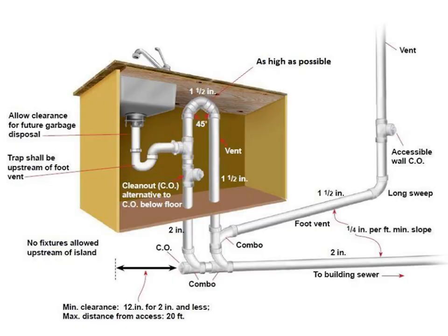The right way. As you see, the vent from the kitchen sink goes as high as it can in the island, then down to the floor like all other drains. It then connects to a vent pipe over on the right, a minimum of 6 inches above the height it had above the sink. But because the vent has a low section, it needs to tee into the drain system at its low spot. It also needs a cleanout as it vents down from the sink so that you can clear the low section of the pipe if you need to. There's a good link below to a YouTube video on proper drain and vent for an island sink.